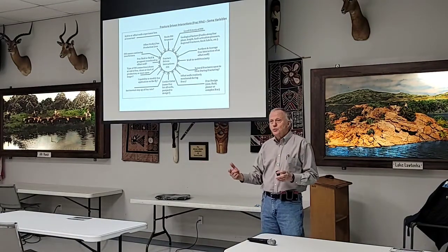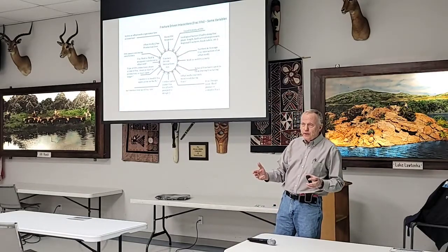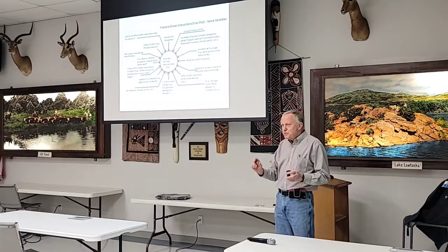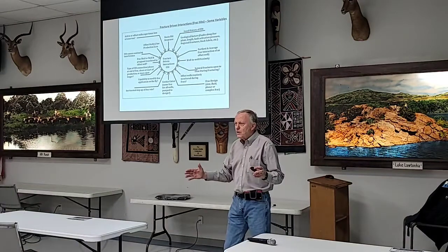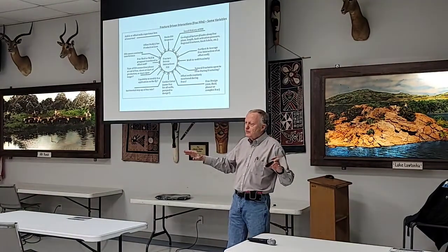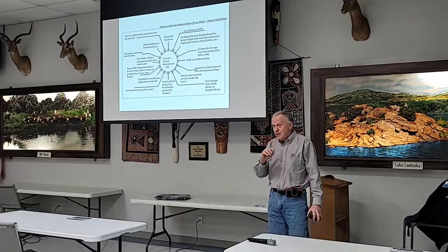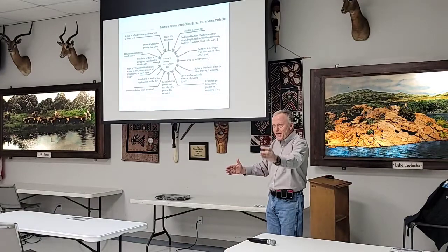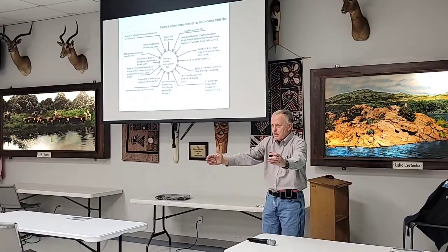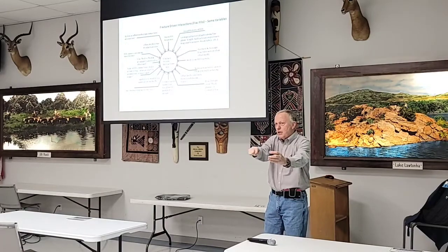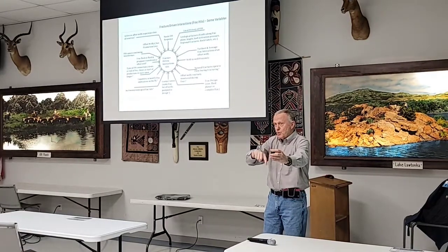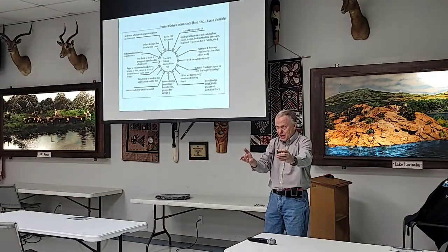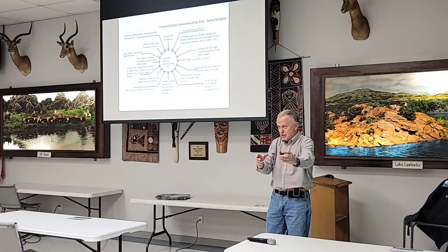But in some areas like the Woodford, the Niobrara, and the Eagle Ford, you've got a very high possibility you're going to lose some production. And the reason behind that is water transfer. There's a lot of little factors you go into. I had to cut out a couple of slides here to make the time element work. But if you're fracturing, you've got an old passive well right here and you've got your new well right here, look for the areas of the passive well, the older well, that have been depleted. Take a little bit of diagnostics and some tracers to be able to see this.